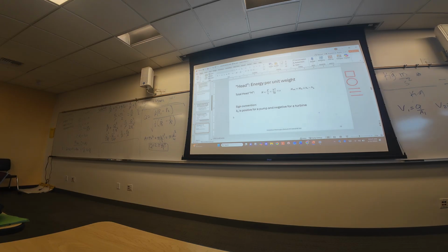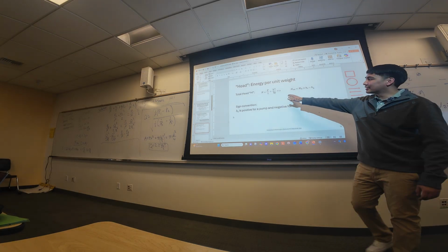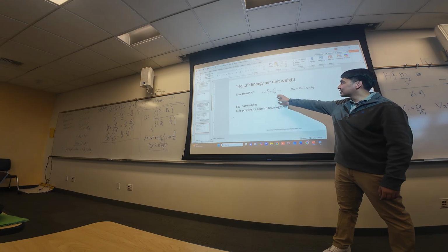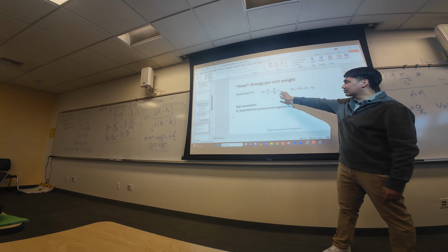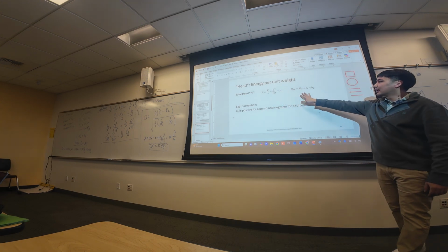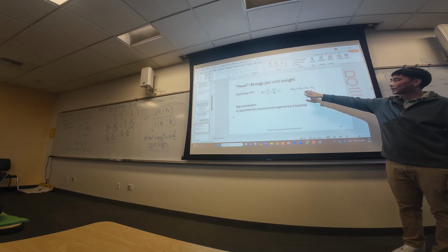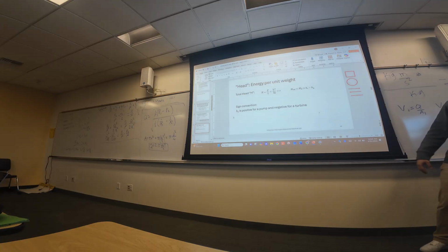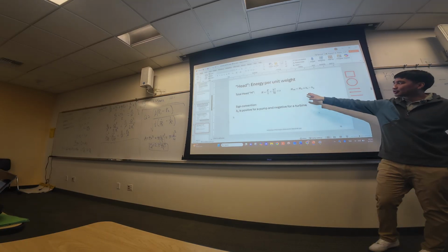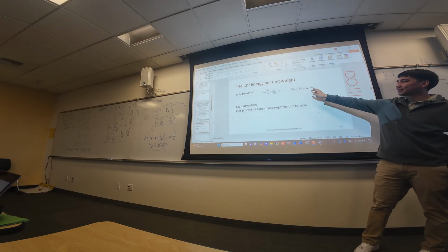Okay, so here I found more equations for the total head, which is essentially your pressure divided by specific weight, and it's basically the one term, one side of your Bernoulli's equation, right? Plus V squared divided by 2g plus z. You can have your total head out equals your total head in minus these two terms, right? Which is the shaft work in minus the HL. So you could think about it as total head out equals total head in, minus extra head put in, minus the friction.